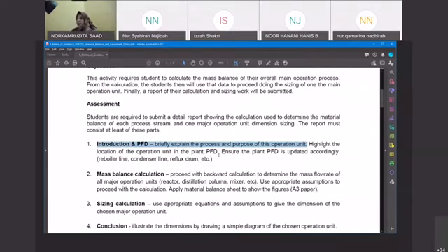So you need to include that in your plant PFD. Based on that, now you can see where this reboiler line comes from, and where this condenser line comes from. The condenser needs water, so it must come from the utility.